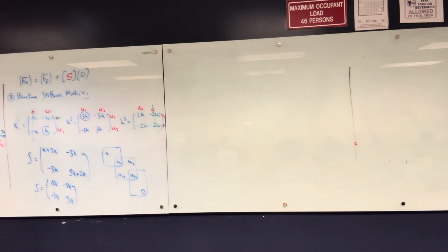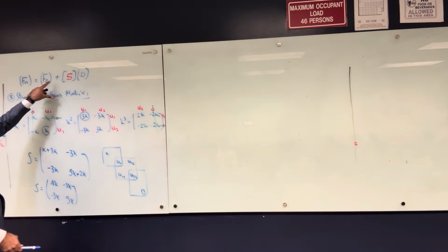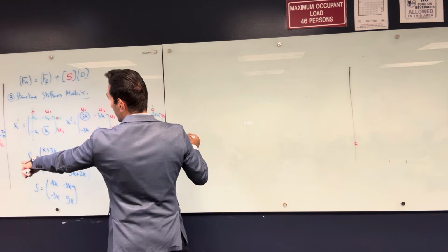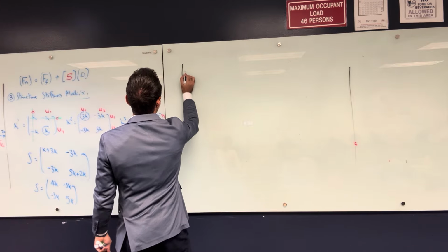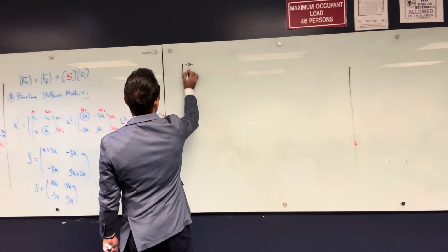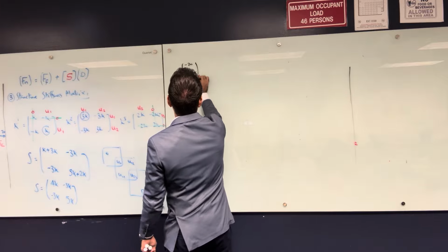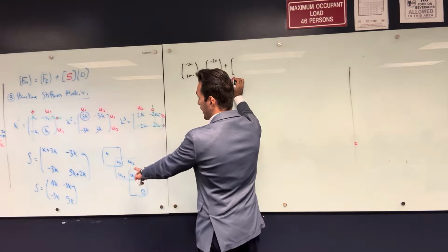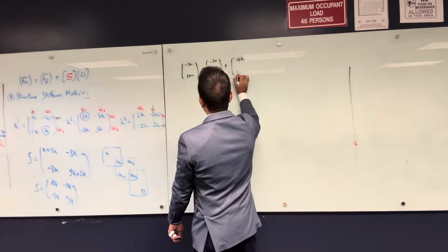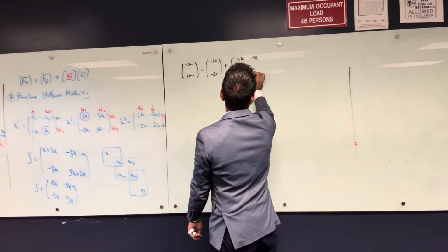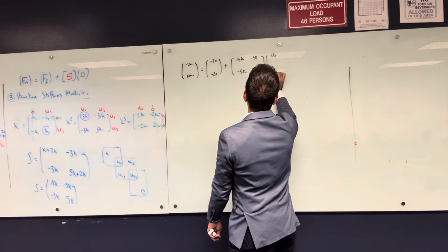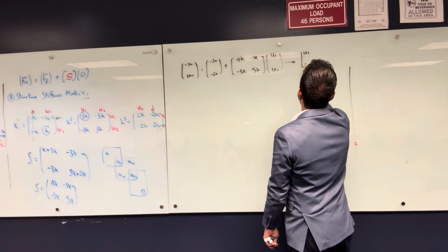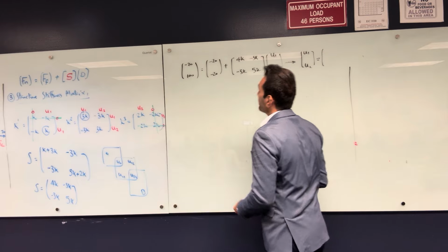All right, so right now I have Fn and I have Ff and I have S. I'm ready to get the displacement. So all I have to do is build these one element by element. So Fn is equal to negative 20 and 100. And the fixed end forces, as far as I remember, negative 20 and negative 20. Correct. And then S is going to be 4K, negative 3K, negative 3K and 5K. And then I have here U1 and U2. You use your calculator and solve two equations and two unknowns. And then you are going to find U1 and U2.